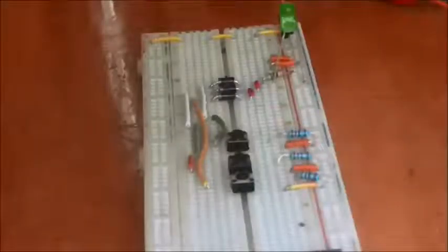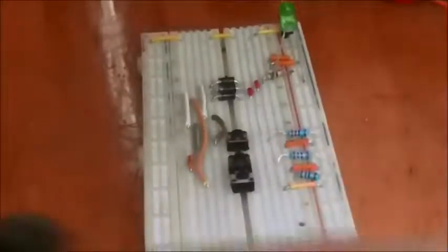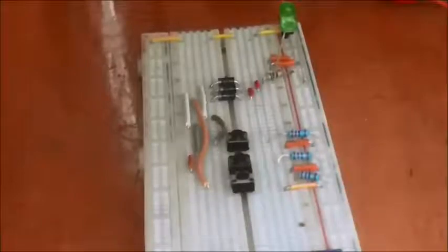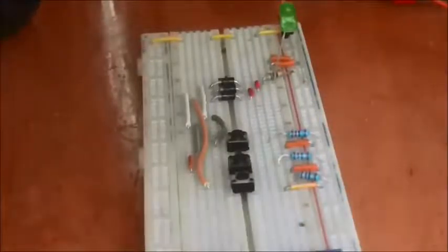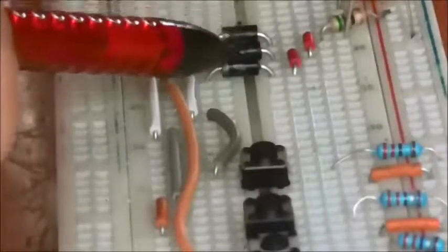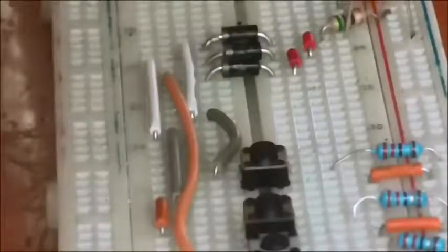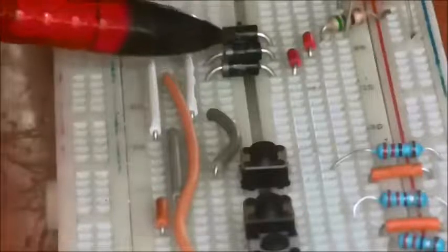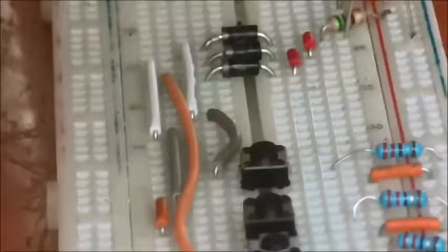To begin with then, we'll go with some very old school technology, and what we've got here is an AND gate and it's constructed out of diodes. So, I'll zoom in a little bit here so that we can see what we've got. We've got three just plain, normal, bog standard barrier diodes. They're nothing special, they're 1N4001s.